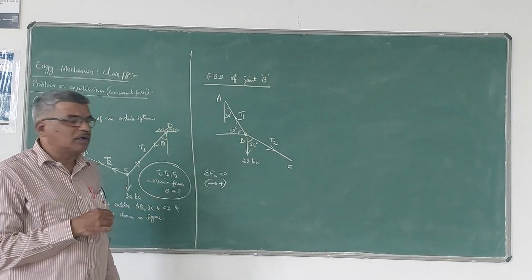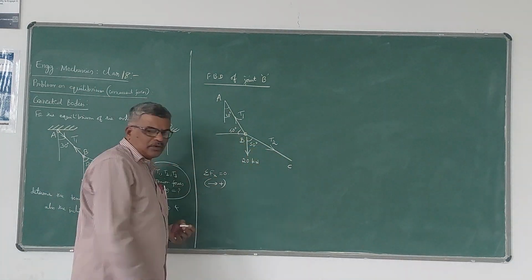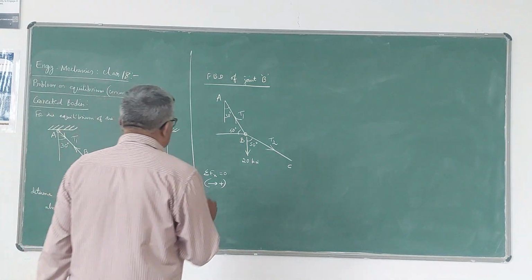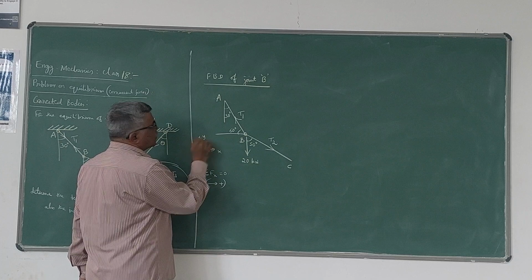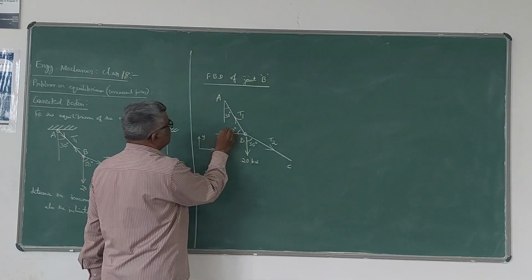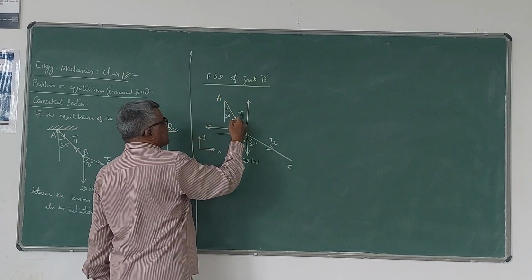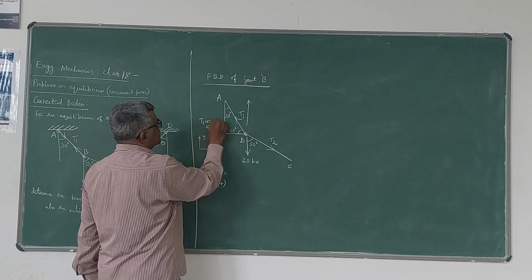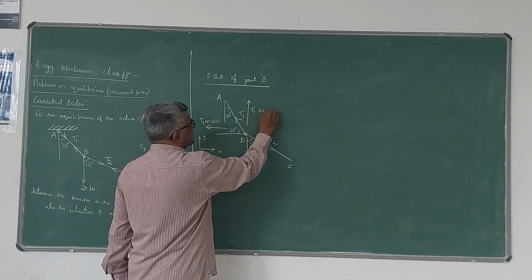Forces acting towards the right are positive. Now here we have to resolve T1 and T2 along horizontal and vertical directions. Let me take the global x-axis and global y-axis. If you resolve this T1, it will be like this, it is in the second quadrant. So this becomes T1 cos 60, because 60 degrees is the angle made with the horizontal, and this becomes T1 sin 60.